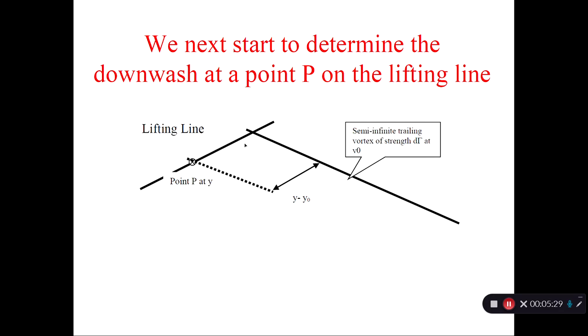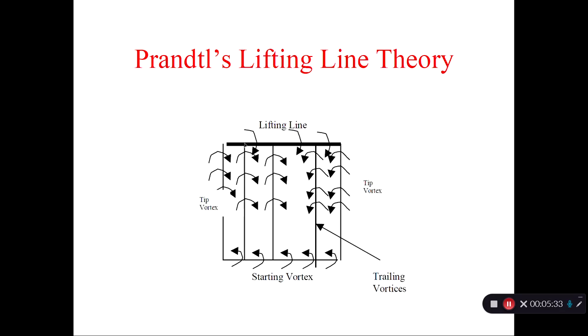Now we are going to take one single vortex of these. There's an infinite number of them. This is really a vortex sheet. There are lines of vortices running from the wing to infinity, because the airplane is infinitely far away, relatively speaking, from where it started. So these lines are going from x equal to 0 to x equal to infinity.